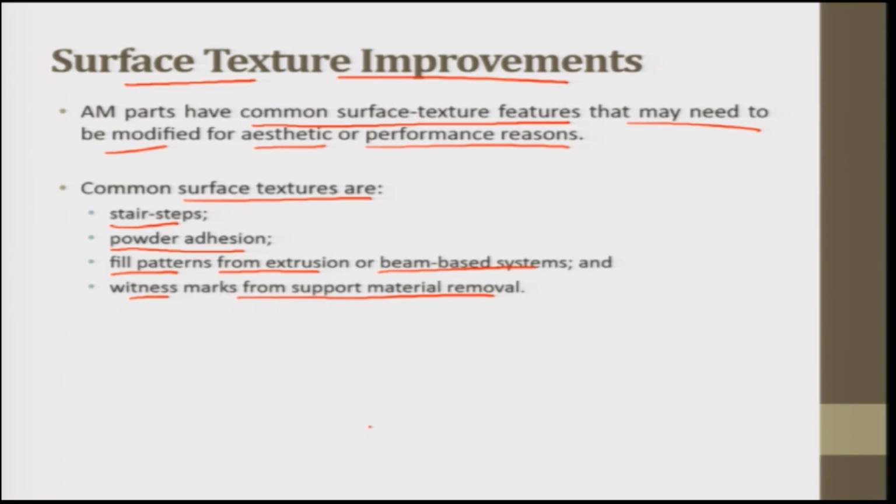The staircase effect that I discussed is a fundamental issue in layered manufacturing and it is difficult to overcome sometimes, although one can choose a thin layer thickness to minimize the error at the expense of build time. The thinner the layer is, the more the time, but we will have a better finish in that case. But it is better to optimize the cost with respect to time and quality.